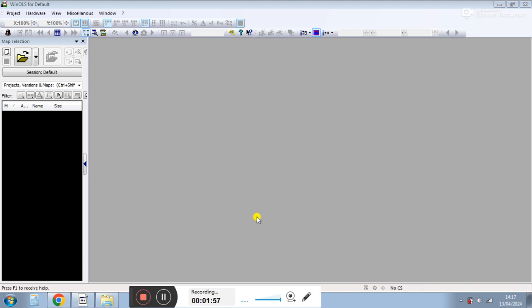Hopefully you've already watched my videos on how to get the files from the car. I put them up on OBD, bench mode, boot mode. The differences in the files, remember OBD usually is only the map data area only, but it can contain more info. I like bench mode because you get full info without opening it, and of course sometimes you just have to open them and do full boot mode.